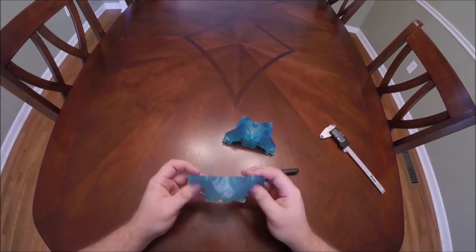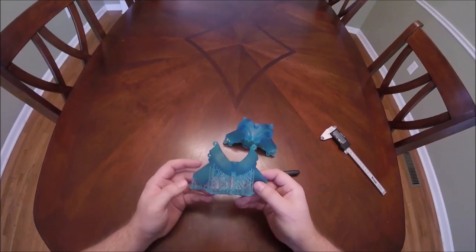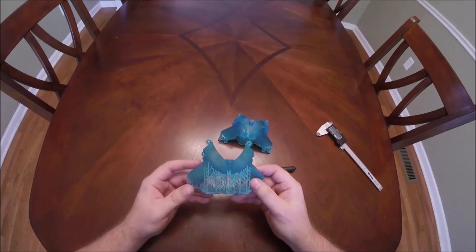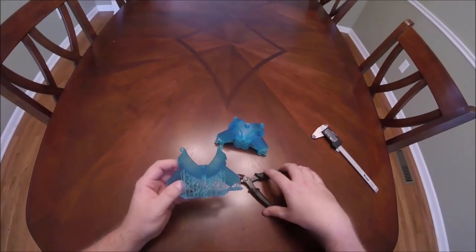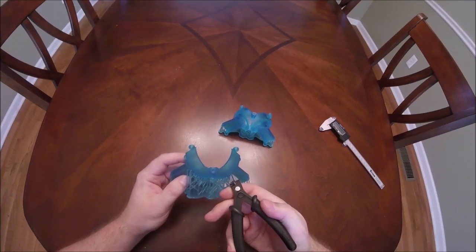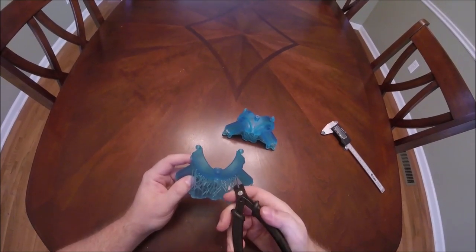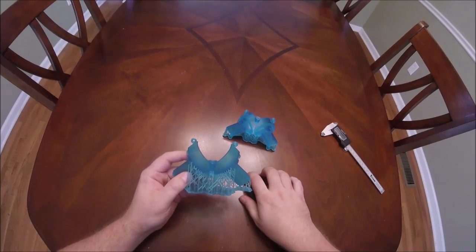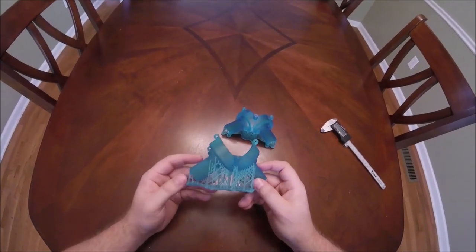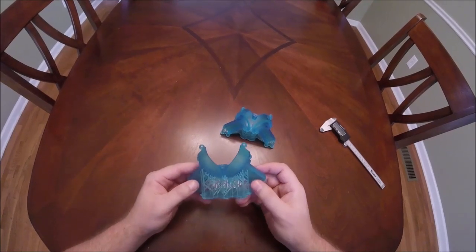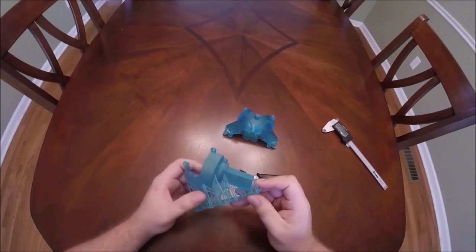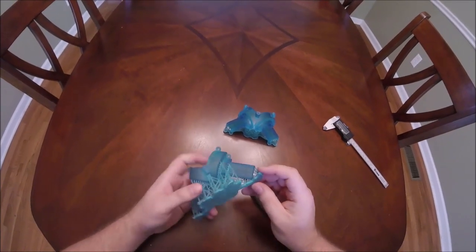If I'm doing something really delicate and small, like a mini figurine or a character of some sort, I might actually go in and clip the supports kind of long, sort of out here in this area, and then actually come back with an X-Acto knife later and clean them all up really nicely. This really just depends on the type of model and how large it is, that sort of thing. For this model, like I said, for the most part, I'm going to be fatiguing and breaking the supports off, and you'll see kind of the process I take.